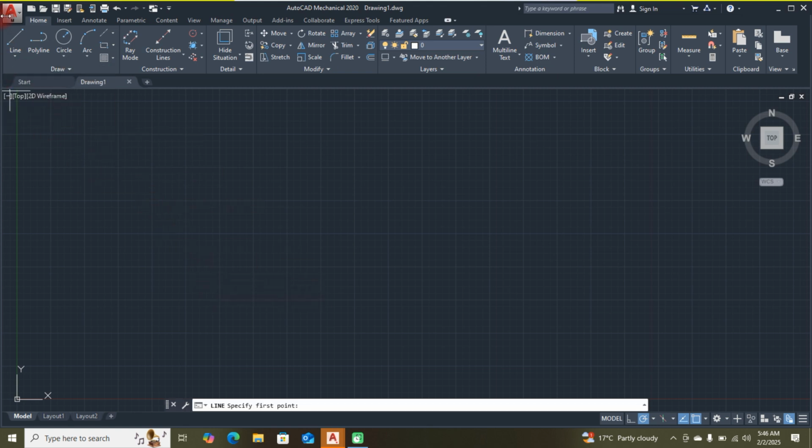When you pick this line command, there are other features which control it. For example, I want to create a line that is perpendicular to one and to another one. So I must enable this. This is auto on. Auto on mode enables you to create this line.